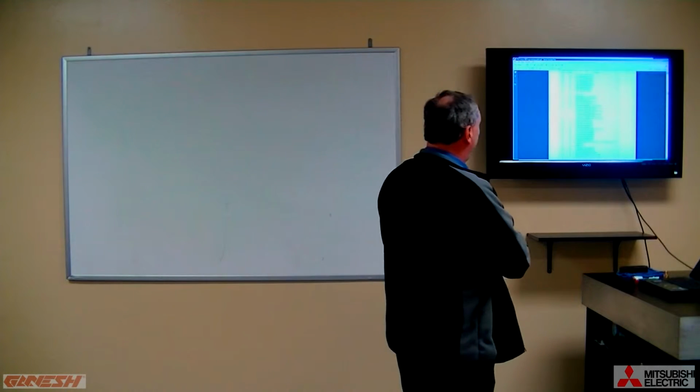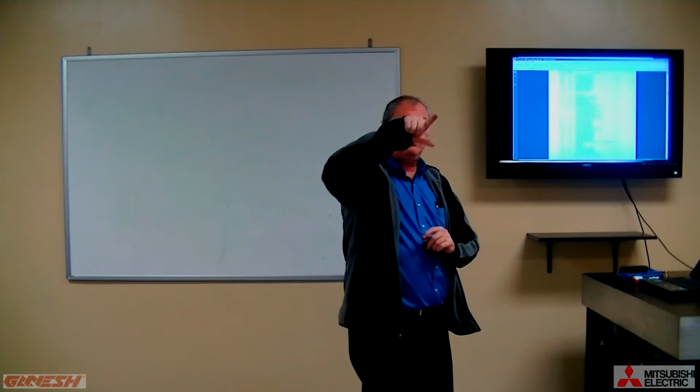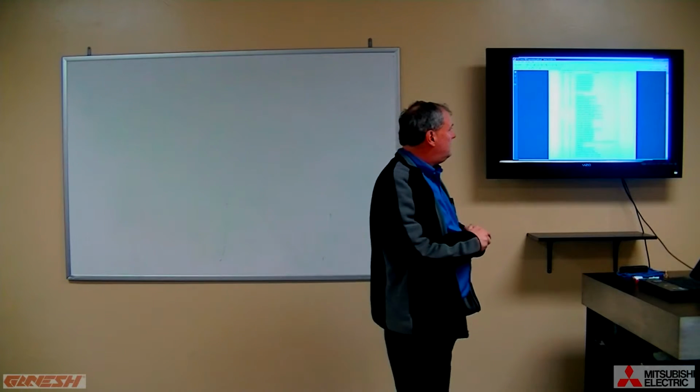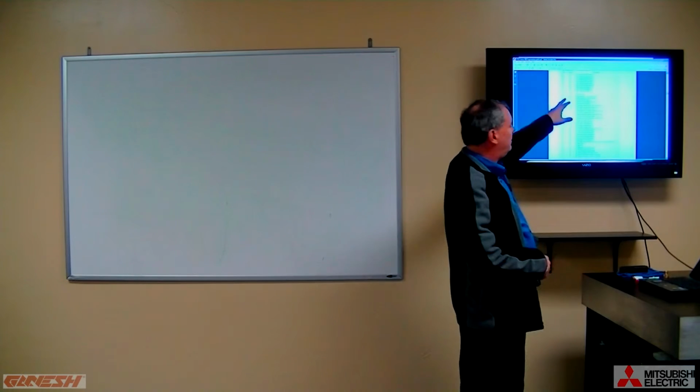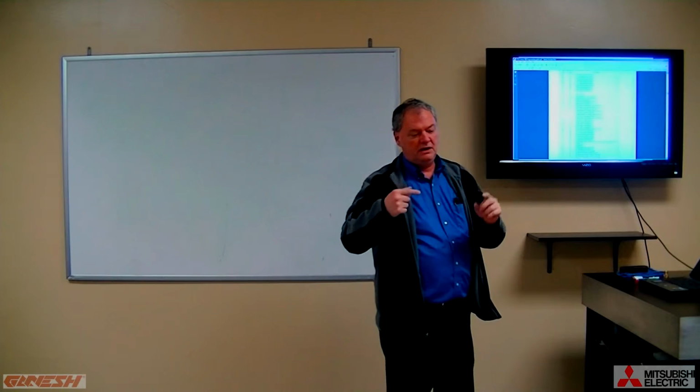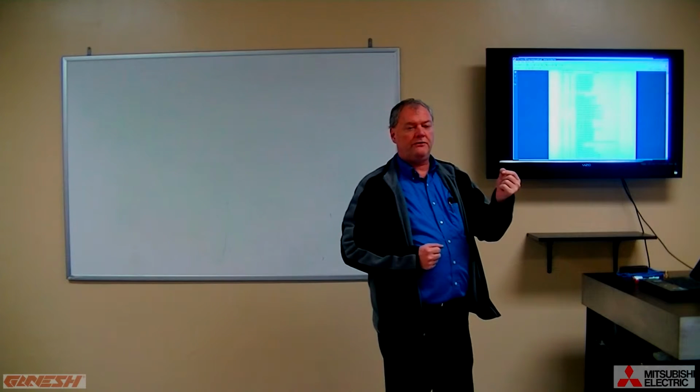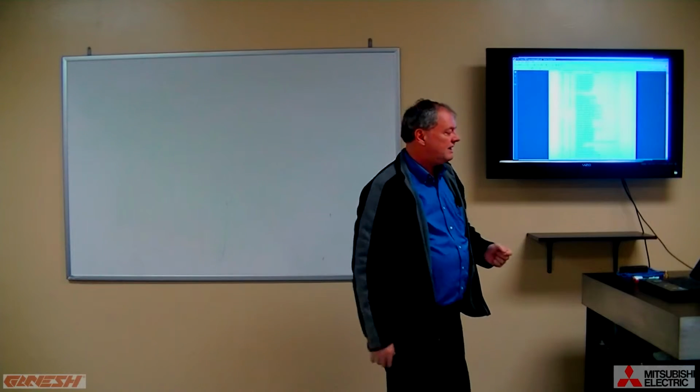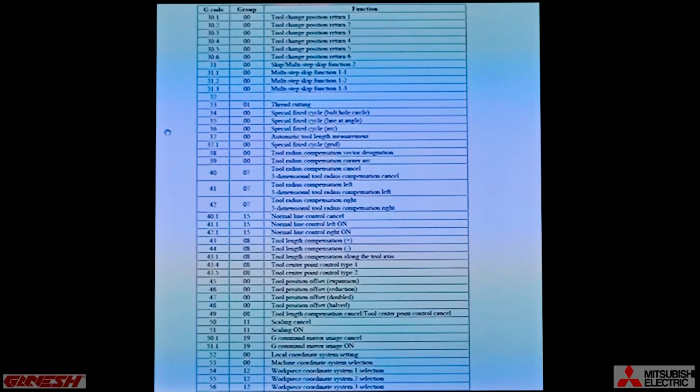the calculation for you. Likewise with holes that you drill at an angle, maybe a series of holes along an angular line, that's what G35 does. All you have to do is tell it how many holes, the starting location of the first hole, and the angle that it is to the X-axis, and it will drill along those holes.